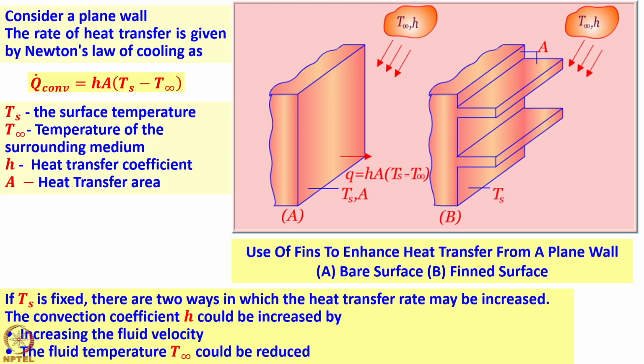To understand that, this is a scenario where you have a base surface where there is no fin, and now these are the fins which you have put, that is, you have extended the surface by extra material. So why does this necessity come? Let us write down the heading as extended surfaces, or fins.